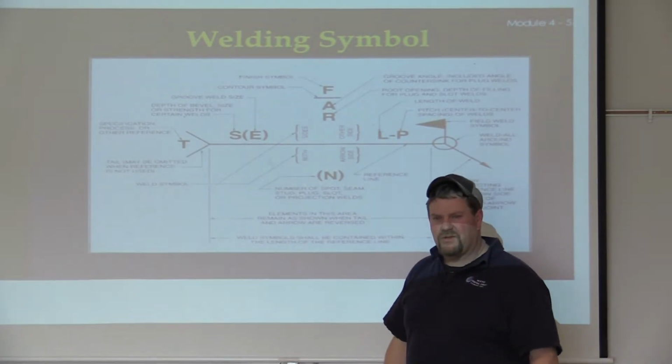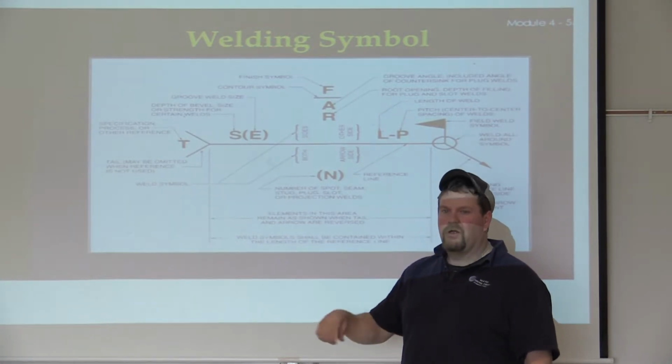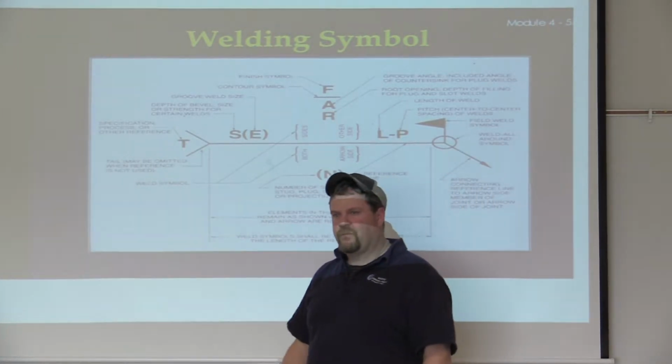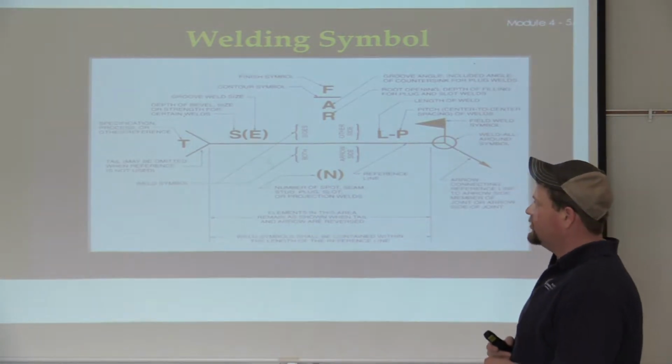You're going, what in the world is that? It means fill that plug weld up roughly halfway. So a 2-inch thick liner, fill it up 1 inch of weld, okay? Particularly things used in road equipment and stuff like that, you'll see from time to time.